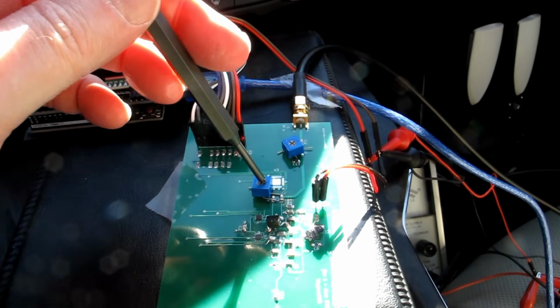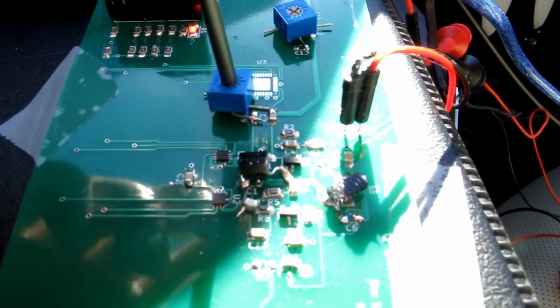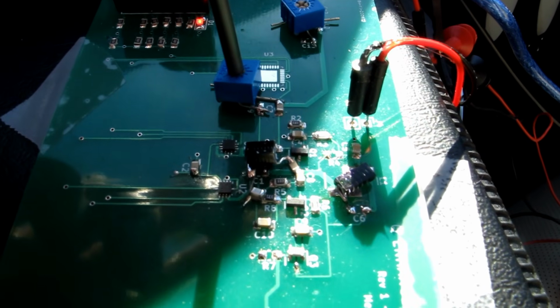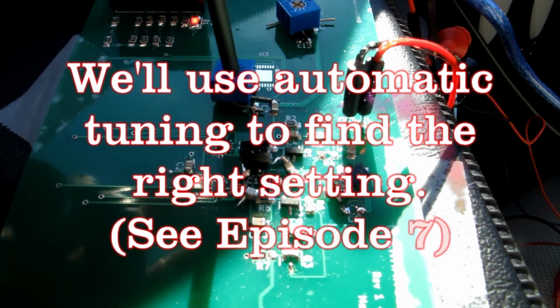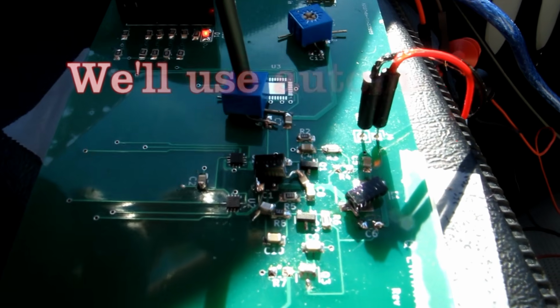Okay, so there's another pot here. This is the Q enhancement pot. So let me vary it. I'll turn it up a little bit. So it went into oscillation, so that's why it went blank. If I turn it back, so now we've got good Q enhancement.